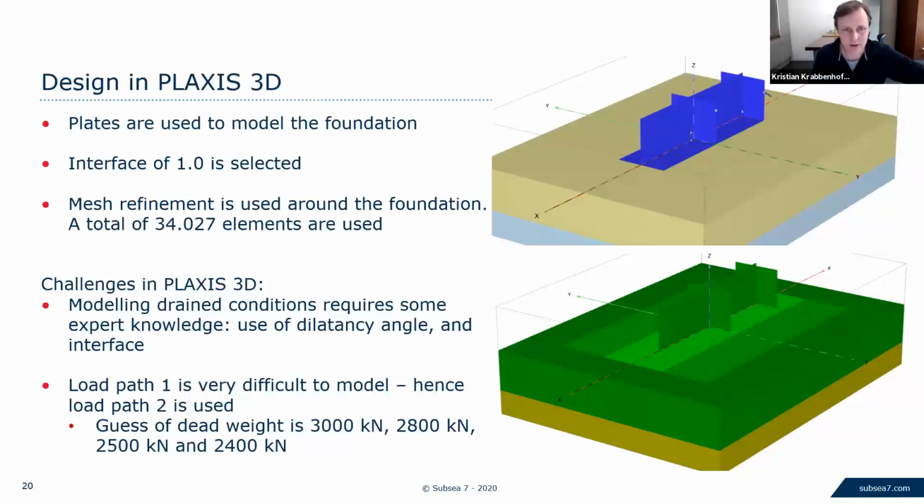You're asking for the factor of safety. Whereas if you only have load displacement analysis at your disposal, you will have to somehow come up with a fictitious simulation to get to the ultimate limit state. Sometimes that's straightforward. In other cases, it's less than straightforward. And in those cases, limit analysis really is, I believe, a powerful tool.